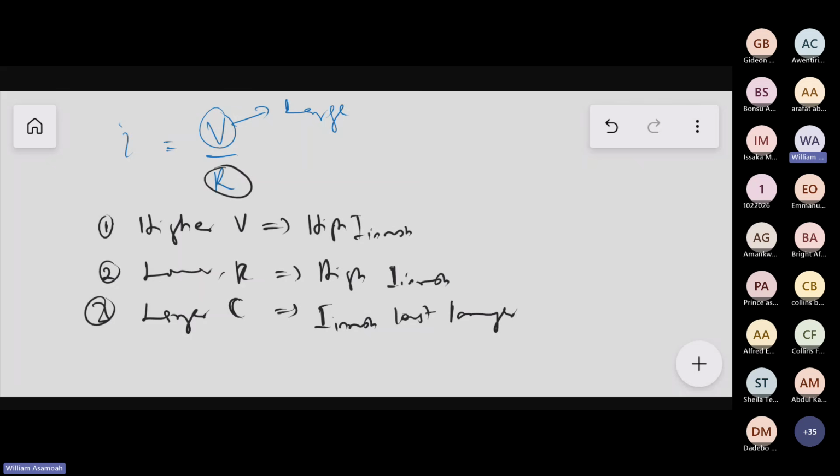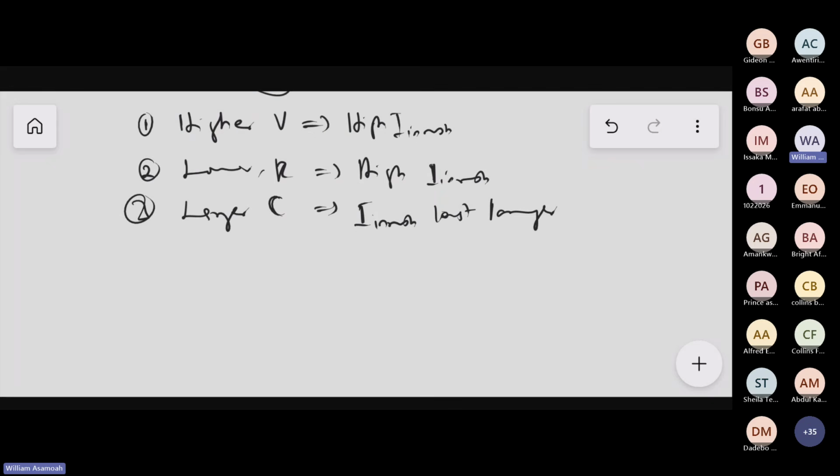So in industry, we have to limit it. When capacitors charge suddenly, several undesirable effects may occur. One, contact damage and arcing. Because of the huge current flowing, the contacts can be damaged. It can burn the contacts of the switches, and at times it will seal them shut. Then fuses and circuit breakers will trip. It can cause voltage sag on shared supply lines, semiconductors will have some stress, and it can also produce electromagnetic interference. Some of these questions you get in the objectives.